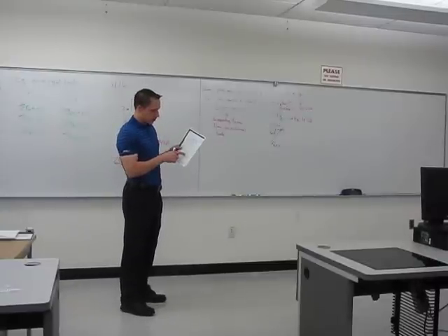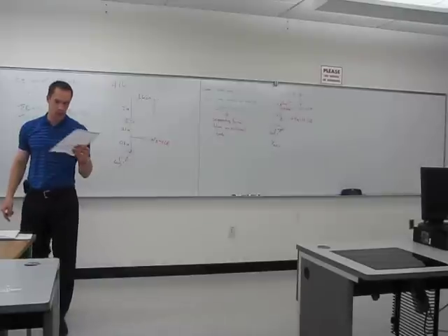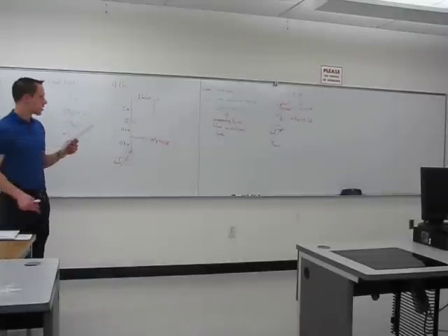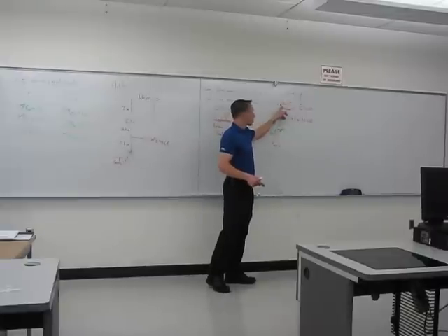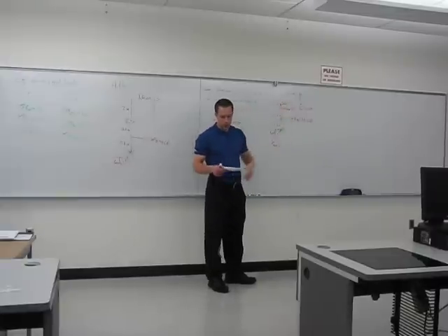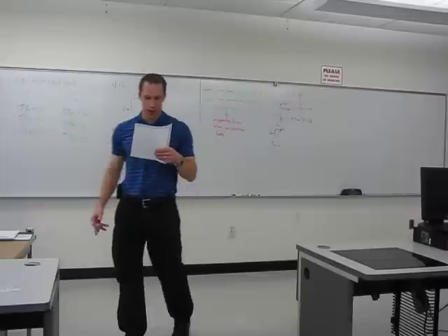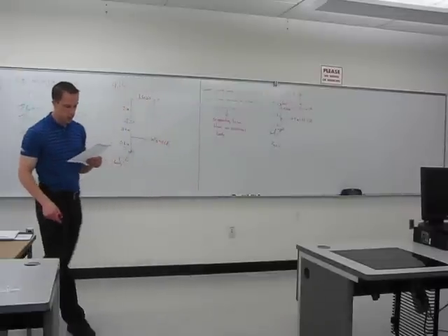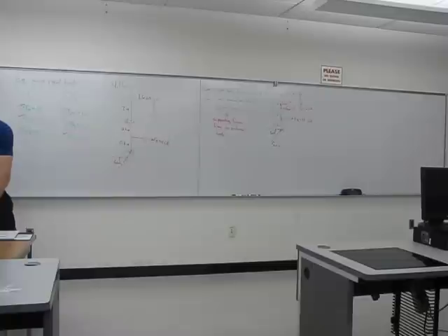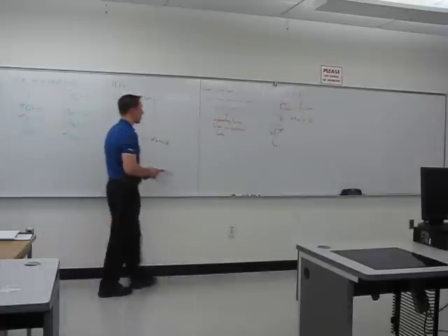And then the last one, a fixed support. We might see one example of that later, but it's basically the same thing as a pin, but there's also a moment associated with it. We'll see that one later, maybe. But at least for now, if we can handle the first 4 categories, as we practice this, you'll see it's not so bad. But if I were you, I would be prepared to know the different reaction forces.